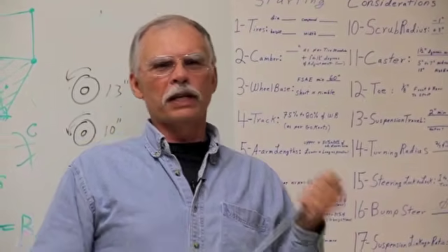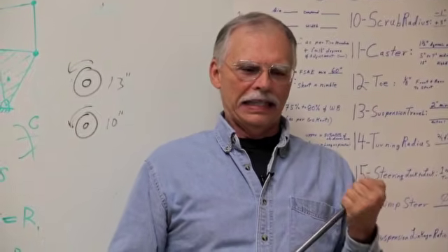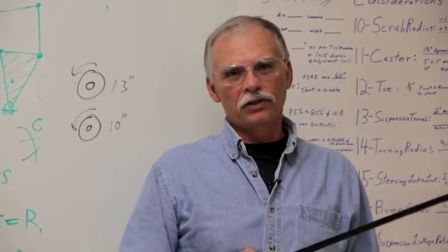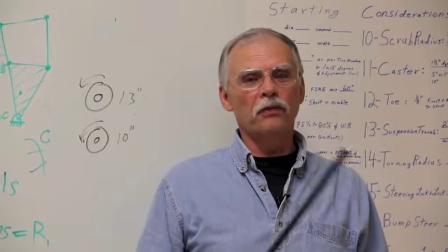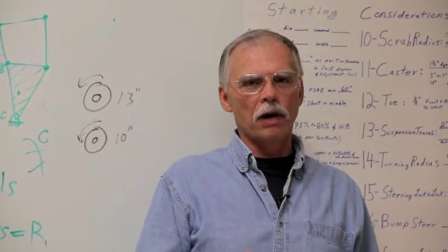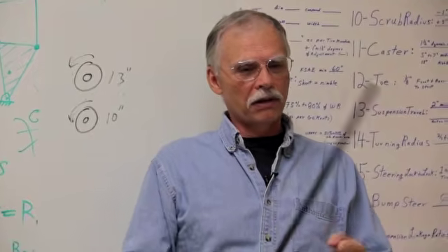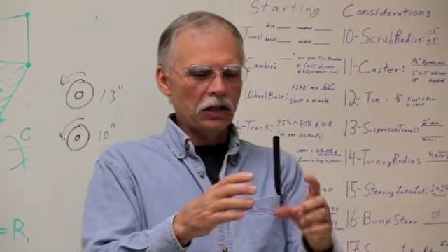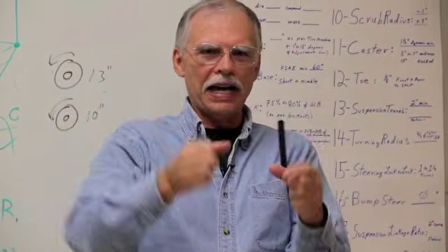The other thing is a lot of teams like to use these little tiny coffee can lid size steering wheels like this, and they've got enough geometry and they've got big slicks. One driver came out of the endurance event and said, if it had gone one more lap, my arms would have fallen off. Why? Because the steering effort is so bloody high. Look at these things. This is all part of the development process when you're testing the car, is to make the darn thing work for the driver.